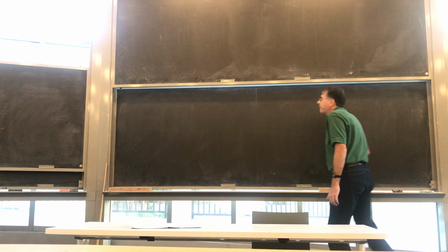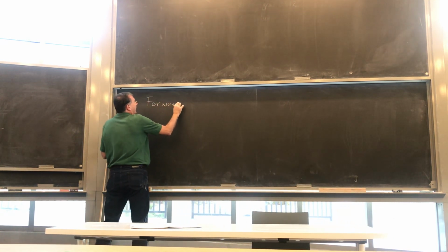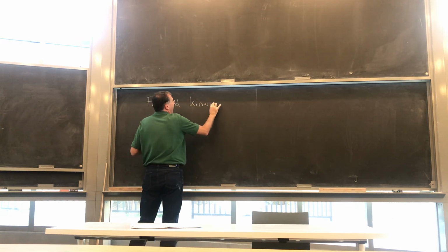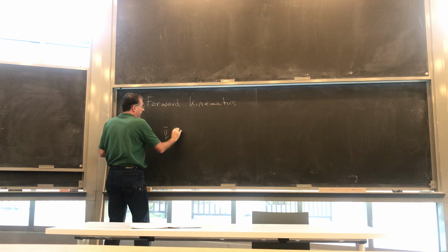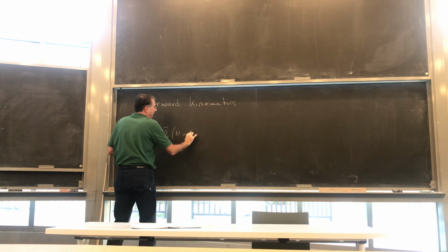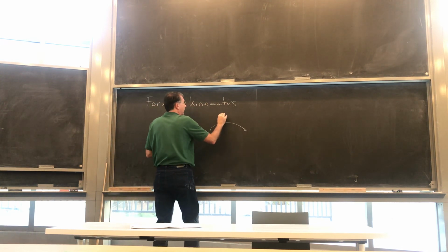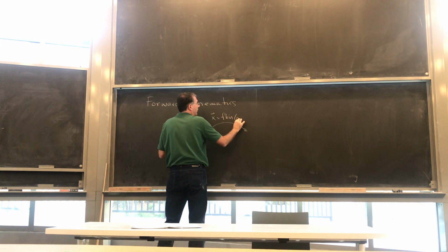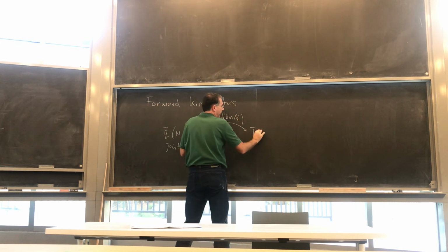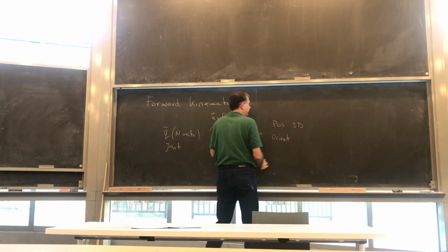So what I'm going to start with is the forward kinematics, right? Meaning you take your joint vector, which is an n vector, and basically calculate an fkin, x vector is an fkin of q vector if you want, to your tip, where that is both position in 3D and the orientation.